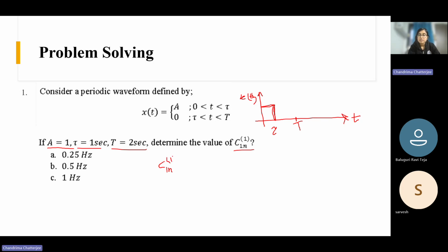So in the lecture, if you see, when we need to find out the Fourier coefficients of any waveform, this kind of pulse waveform or trapezoidal waveform or clock waveform, what we will do is keep on differentiating these waveforms until we obtain an impulse function.